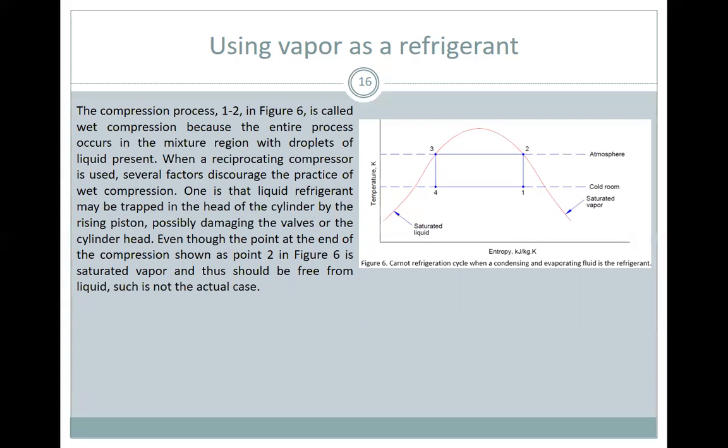Yeah. When a reciprocating compressor is used, several factors discourage the practice of wet compression kasi may epekto sa compressor pag wet yung refrigerant. One is that liquid refrigerant may be trapped in the head of the cylinder by the rising piston, possibly damaging the valves or the cylinder head. Even though the point at the end of the compression shown as point 2 in figure 6 is saturated vapor and thus should be free from liquid, such is not the actual case.